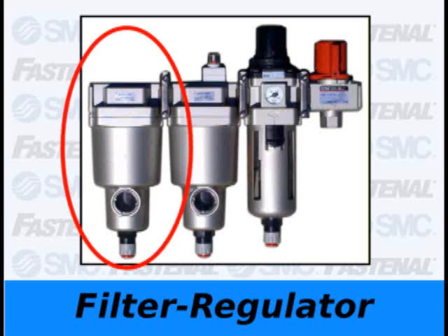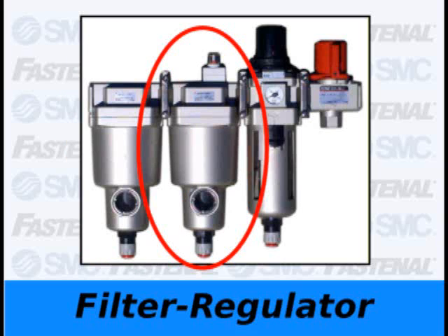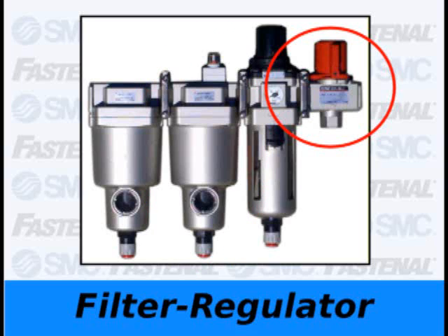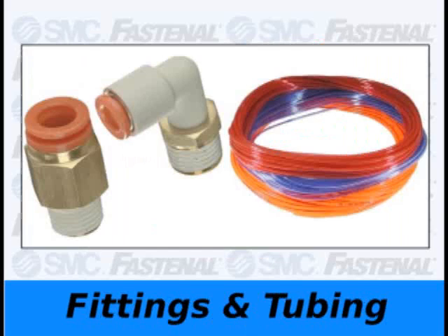On the left, there is an AMG series water separator that takes out 99% of any water droplets in the airline. Next, there is an AMD series oil mist separator, sometimes called a coalescing filter, and that takes out 99.9% of superfine dust and sticky oil that comes out of the compressor. And just like every branch line, it should have an OSHA lockout-tagout shutoff valve.